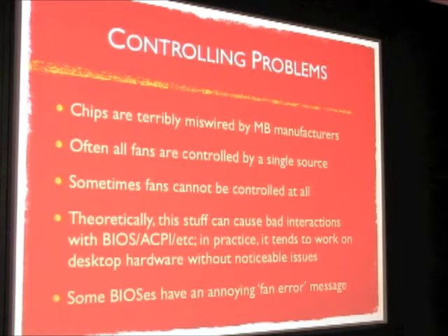As you recall from the previous slides, most chips provide several fan controls for several sensors. So you can have a separate fan control for system temperature, for the system fan, and for the CPU fan, and a separate fan control for an auxiliary fan and for a different CPU fan. But on a lot of motherboards, all of those fans are physically wired to the same fan controlling source. So if you try to change the percent sensors other than one of those, it's not going to have any effect on the system. All of the fans may be controlled by a single percent sensor.